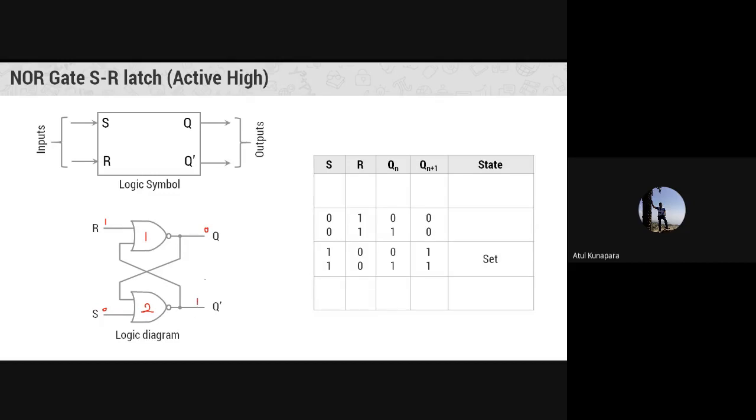This is the earlier condition. So for this case, what will happen? This 1 will come here, so 1 1 will give you output 0, so 0 will remain as it is 0, and that 0 will come here, so you will be getting 0 0, so output remains 1 only. That means there is no change in it. So if earlier your output is 0, then it will be kept 0 only, but if it is 1, then it will be converted to 0.